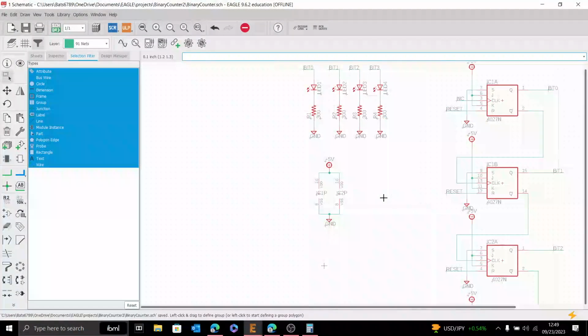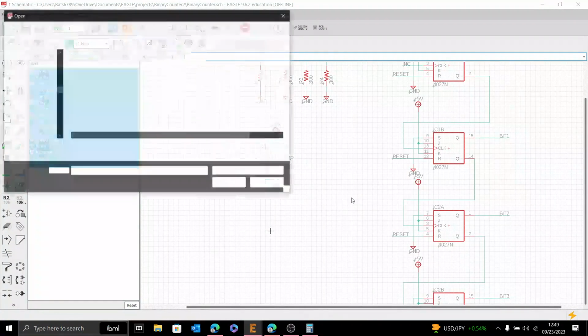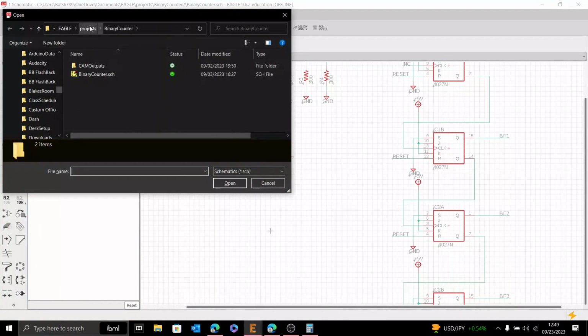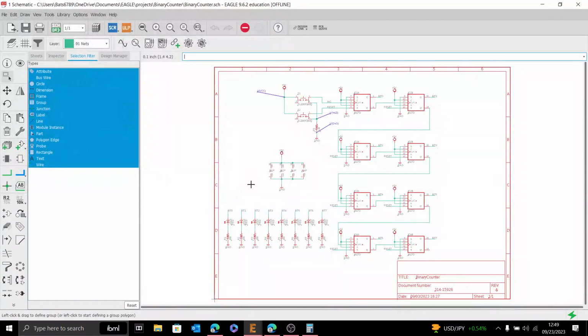And of course, we'll double check my circuit with my known working circuit. So now let's go to the buttons. And before we go to the buttons, I want to give a chance to embarrass myself. So for those that were looking closely at my board, you may have noticed that I scratched off a portion of it. This was the exact schematic. Who can see the problem with my circuit? I'll give you a hint. When I plugged it in, the LED would sometimes be on. I press reset and turn it off, but the increment would never work. Does anyone see why?